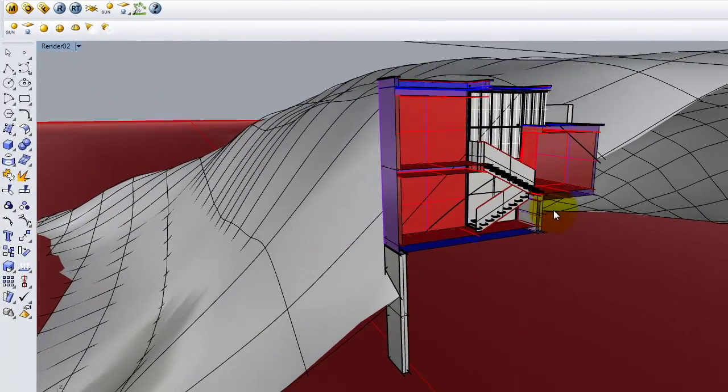Okay? So this is great, except that V-Ray doesn't recognize this as a section. So if I were to render it in V-Ray, I'd get the whole building again. So it's not recognizable in V-Ray. So at this point, everything that I've done to this model is completely reversible, doesn't hurt to do it. But from this point on, the things that I'm going to start to do become irreversible. Right? I'm going to permanently damage the model.